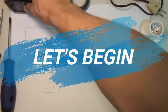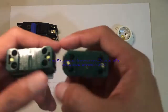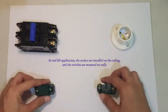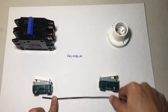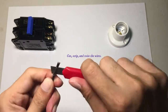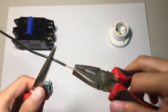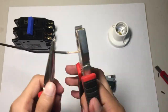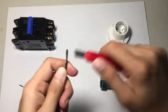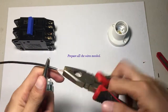Let's begin. Install the components in their respective locations. In real-life application, the sockets are installed on the ceiling and the switches are installed on walls. Cut the appropriate length of wire and strip its ends in order to expose the strands. Twist the strands of wire in order to connect it easily to the terminals of the components. Repeat this step until all the wires needed for the connection are prepared.